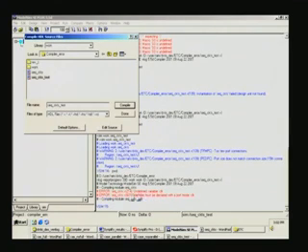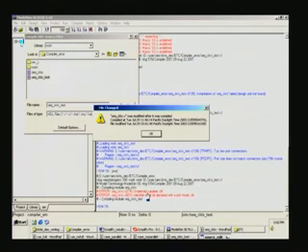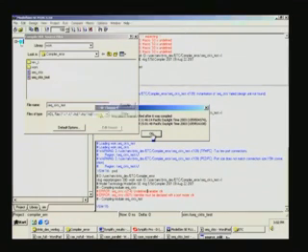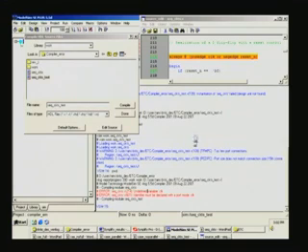See, we changed the name to clock, so it promptly says that undefined variable clock is encountered here. And this is just a warning saying that I have changed the source file. You can just ignore that. It opened the source file and is pointing precisely to the place where CLK is used, because this is an undefined variable.